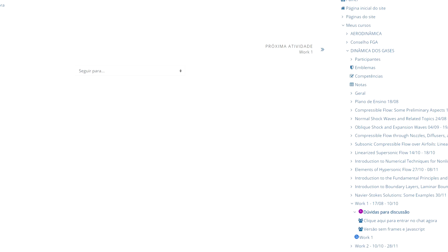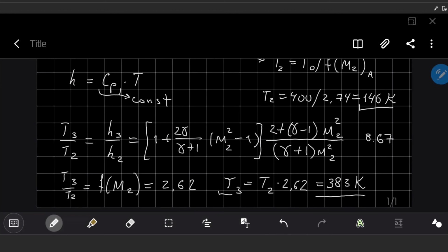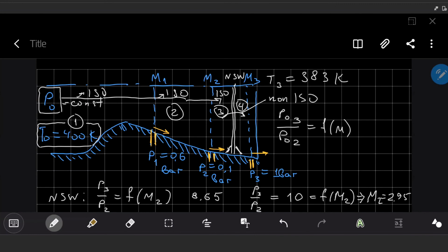You can use isentropic conditions actually everywhere where there is no shock wave or significant flow separation. In the case of high velocity, high temperature, these equations are still working. You just need to make corrections, which we probably have to discuss in the chapter on hypersonic flow. I think that would be a more appropriate time to discuss.